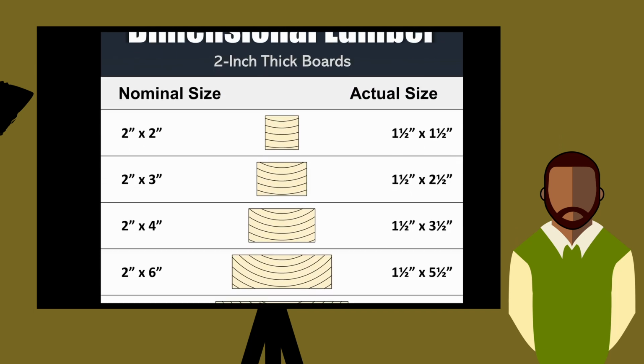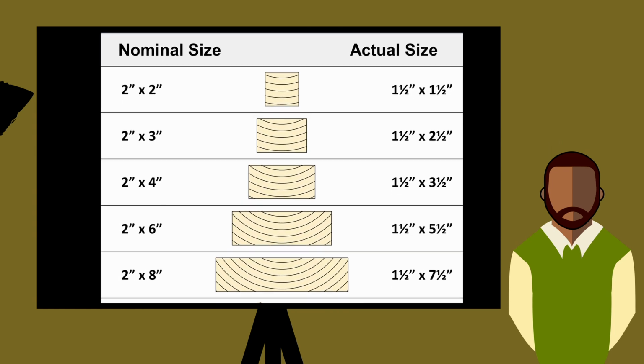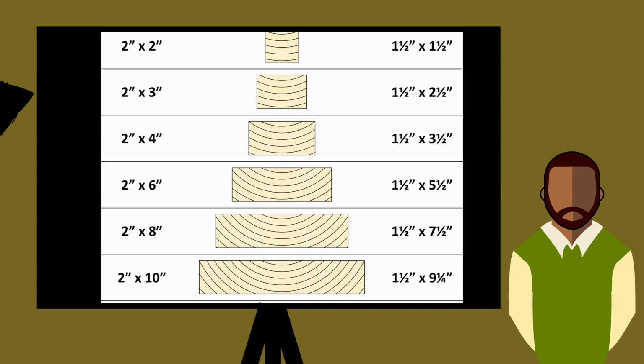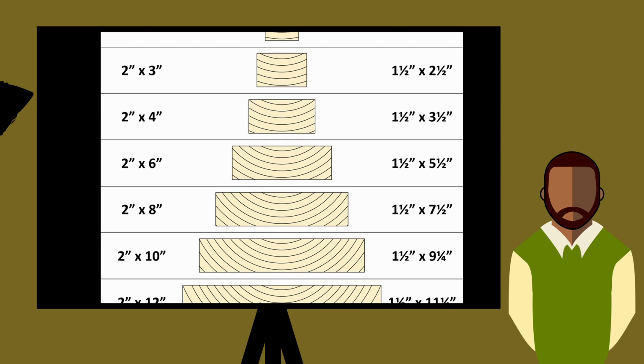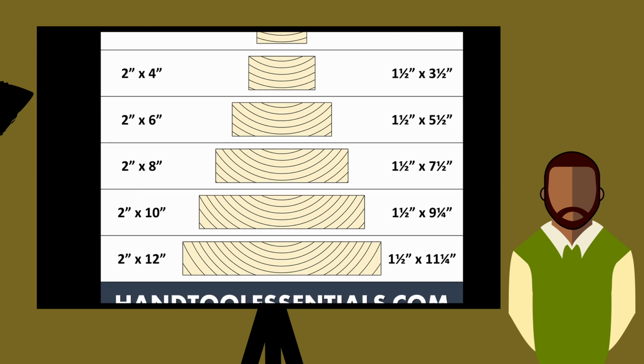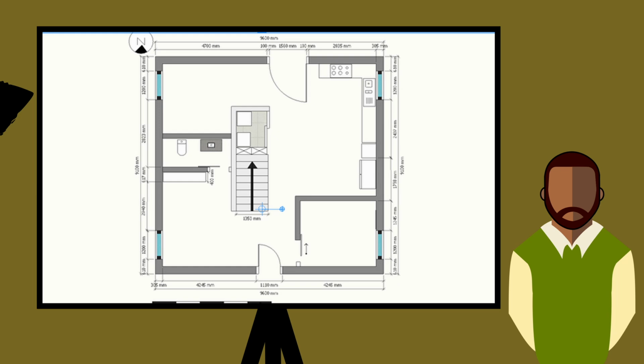Very interesting points in terms of actually even putting this on paper, I think is worth noting. 2x4 is 3.5 inches. 2x6 is 5.5 inches. When it comes to architects and architecture, one thing that really frustrates me is when I'd be sitting at a computer, helping to modify a plan, and the plan would not dimension to the 2x4, it would dimension to the exterior cladding of the 2x4.